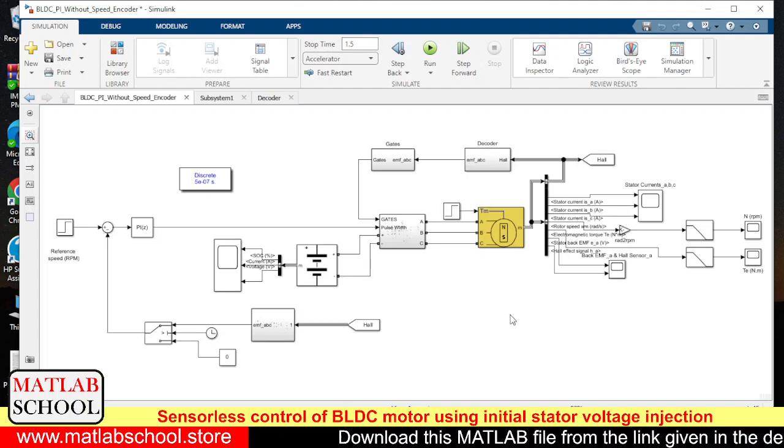Obviously, as you know, since this is a BLDC motor, there's a requirement of Hall sensor to be placed at the rotor. So to detect the position of the rotor, we need to have Hall sensor.